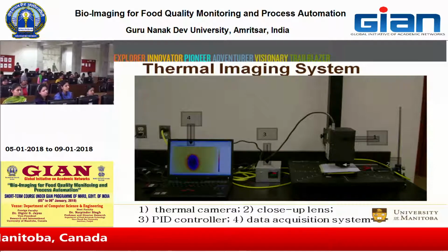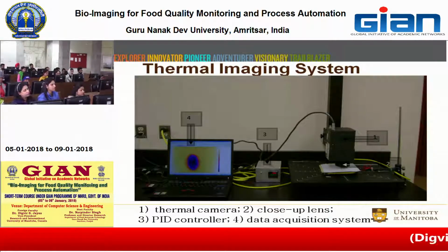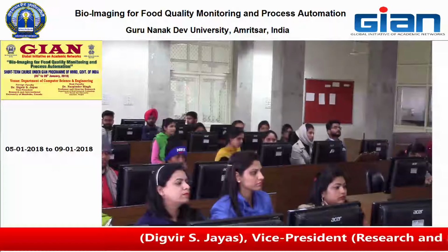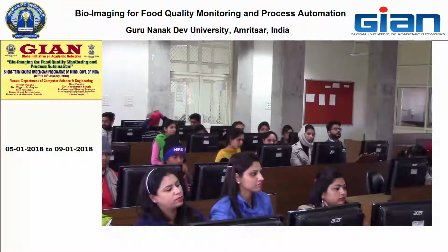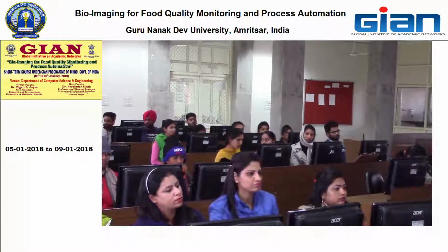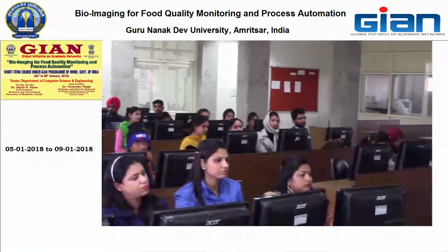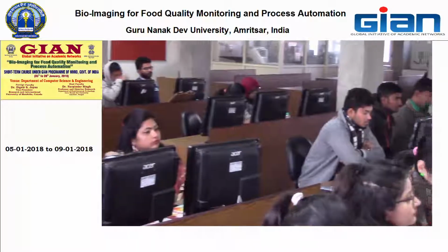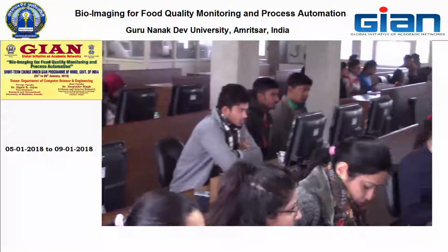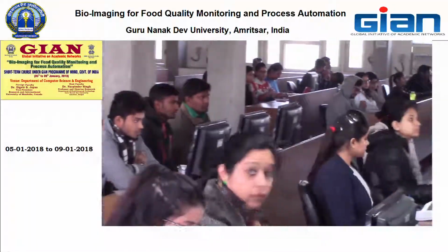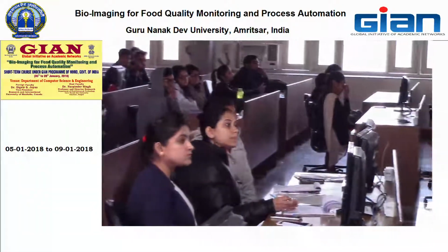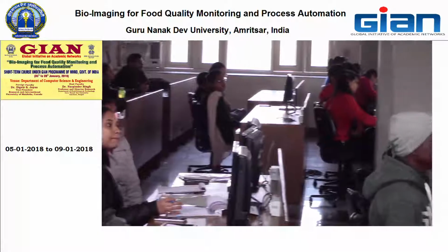And you are basically trying to capture that heat being emitted from that object. Okay? So every object does that, and what you are trying to capture is then the temperature distribution of the material. So the thermal camera basically gives you the temperature distribution or thermograph, and then once you have captured that, you get the image and then you do the analysis.